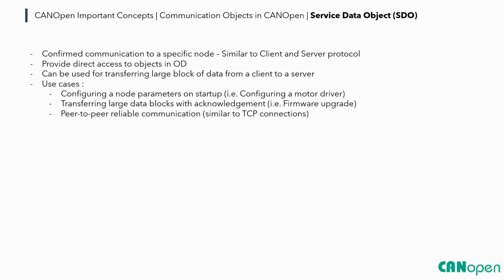All right. So with SDO we can target a certain node specifically. It's not like PDO, where we generate a packet and everybody listens to it. Actually, everybody can listen to it, but in SDO we have this ID and we specify the ID, so a certain node will just take that value and respond to it. Although, as it's transmitted over CAN bus, everyone can receive it, but in the CANOpen stack, that certain node with a certain value will respond.